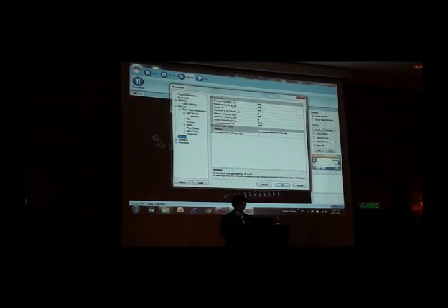The rest is the gradient setting: even level, covered, velocity, cascading drain. So true means we want to have a cascading drain if the gradient cannot pass. If false, that means after it cannot pass, we will propose a drop sum. Okay, and then the cascading drop, we can add it. Let's say I want to choose 150 millimeter.